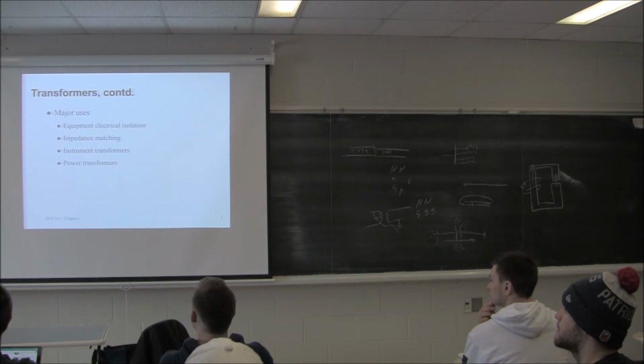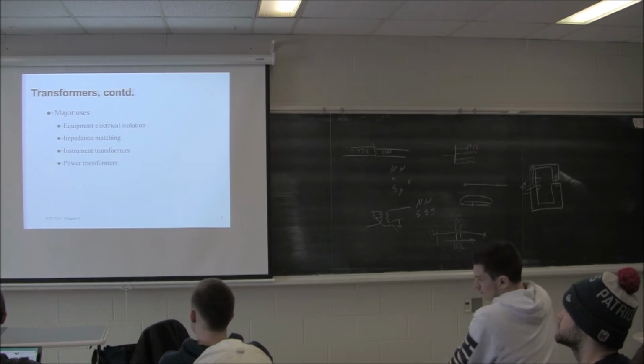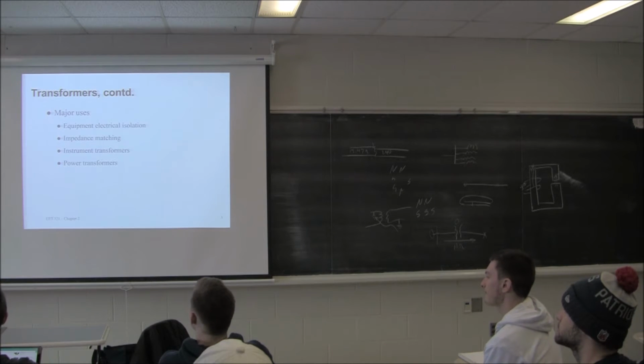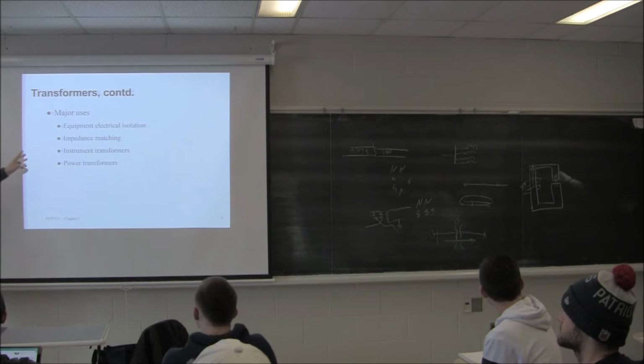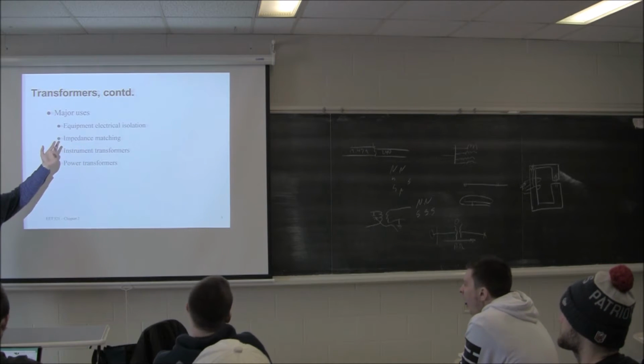Well, if you actually did that, your performance would be reduced because when does max power transfer occur? When your source impedance matches your load impedance. So if you wanted to get the most performance in terms of volume, you can deliver the most power when the speaker matches the output resistance of the amplifier. So really fancy amplifiers, you can select 4 ohms, 6 ohms, 8 ohms, and then you can match it to whatever your speaker is. What are they ultimately doing? They're just changing the taps on a transformer. That's all they're doing. They're being sneaky.